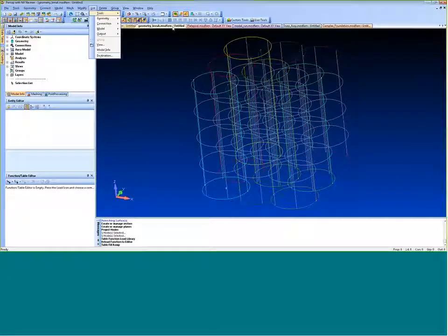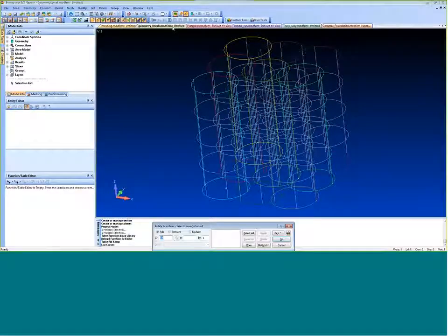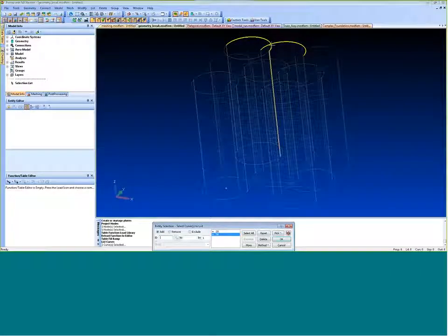Essentially, what happens if we want to list our curves, and I click on those two curves and highlight them, you can see that they overlap, right? This is not necessarily useful if you're going to want to mesh this and have the nodes merged and everything. So previously, you would have to break these curves individually, or at least in groups, and it was a pretty tedious process.